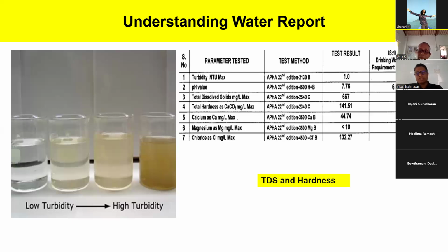That salt reject is calcium chloride, which will increase the chloride in the water. For this reason, salt-based softeners were banned in a few cities in the US because of this calcium chloride water being sent back to the cycle, where it's very difficult to remove higher chloride levels apart from membrane technology. These 7 parameters are high level parameters.